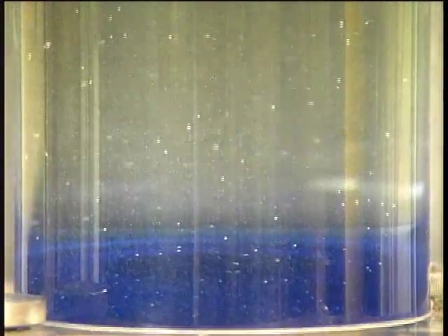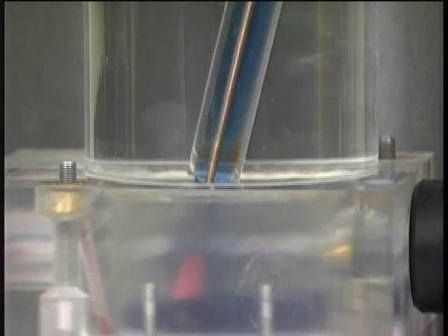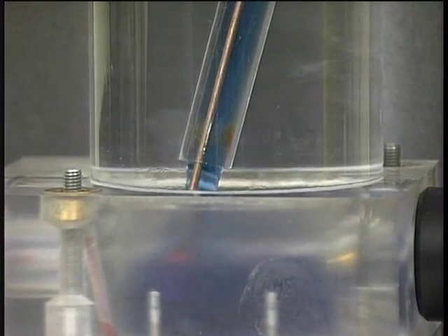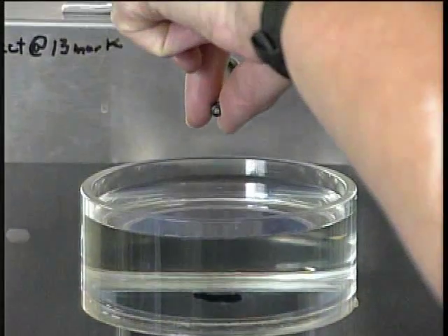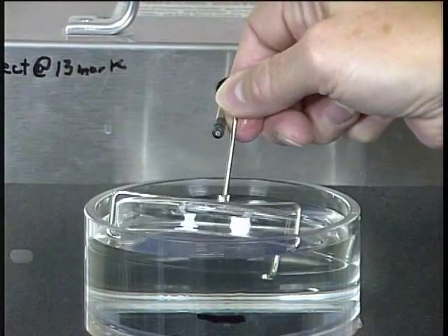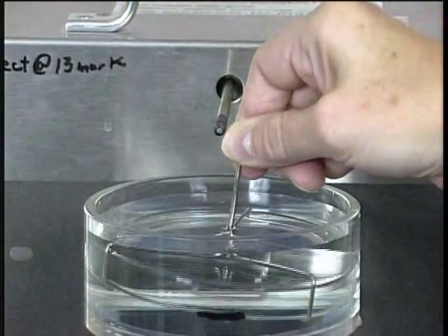The AVA is a sensitive piece of equipment that measures the air in the concrete by weighing the bubbles that are released from the concrete mortar. To do this, a cylinder of water has a more viscous liquid, glycerol, placed at the bottom using a special funnel. A petri dish hung on a scale rod is suspended at the top of the cylinder and collects the bubbles that rise from the sample.